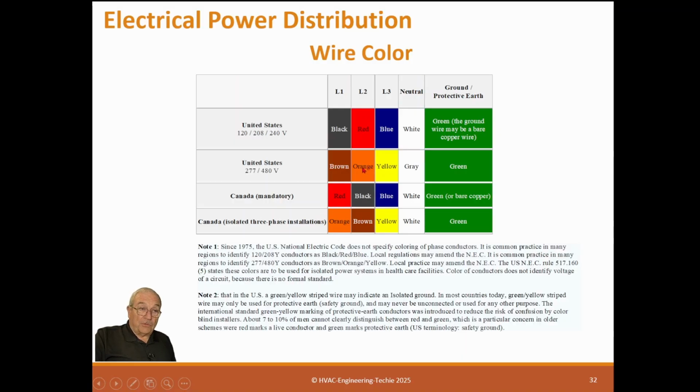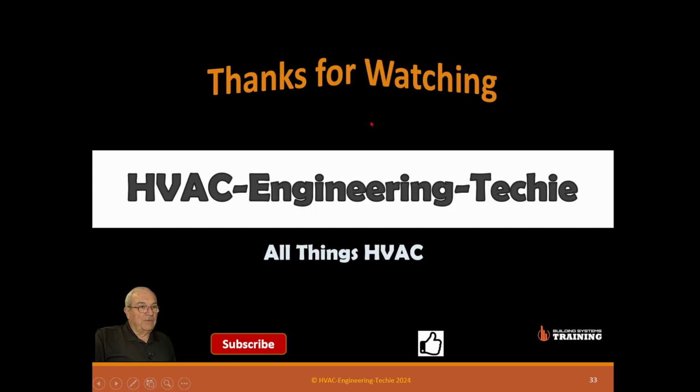You're trying to figure out if the rotation's correct on a panel without a rotary meter. You can watch a contractor that has a rotary meter, he can figure that out, but if you're just trying to figure it out on your own and the colors aren't right, then you're off. You really don't know. And of course, that's one of the tests that need to be done correctly before you start up a panel. Anyway, that's basic distribution equipment for systems.